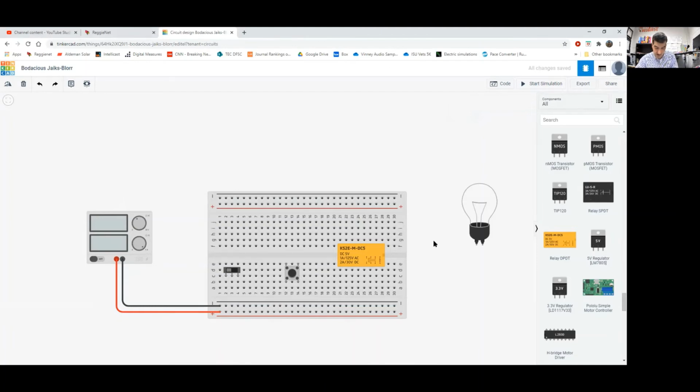Look at the first wire on the first rung in lab 6. It goes from 12 volts to the input or the common of the stop push button, which is the slide switch here. So the common here is right here. So we'll go from right there to 12 volts. So that's our voltage. There's the first wire. That's the upper left wire in the first rung in lab 6.